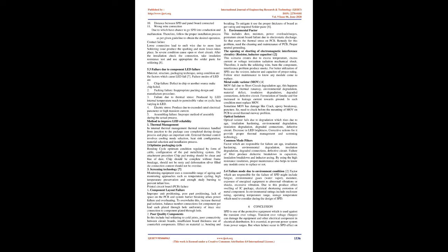3. Open neutral connection. 4. Phase loss conditions. 5. TOV of unloaded transformer. 6. Improper MCOV selection. 7. SPD configured and installed into a delta system. 8. Screw tightening torque. 9. Loose connection. 10. Distance between SPD and the connected panel board.